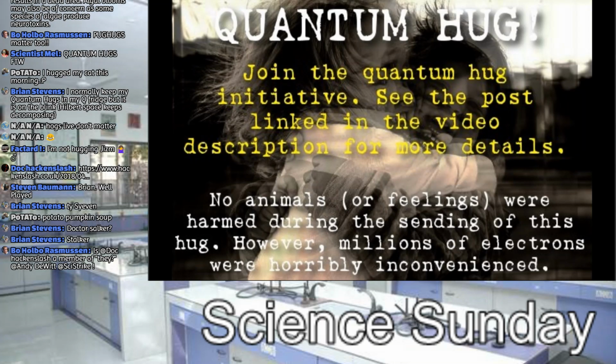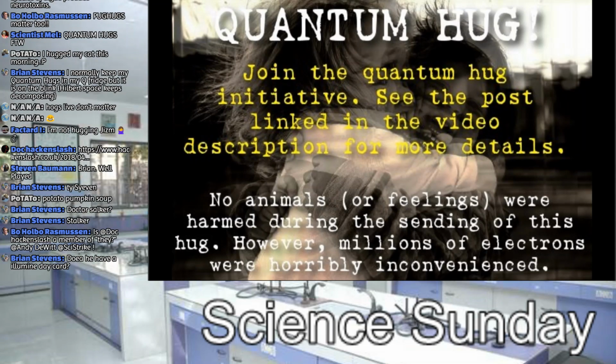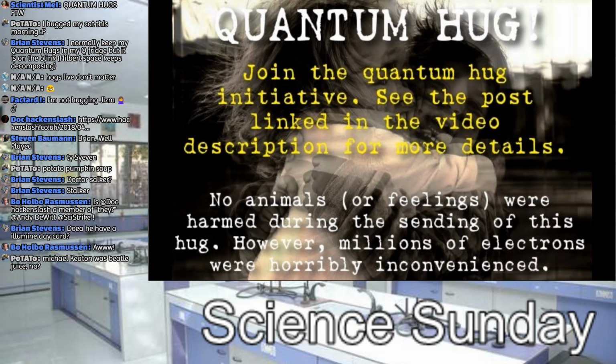Is there any zap? Not today. I told you I was operating while we only had the maximum 10-inch arcs last time was due to a mismatch in resonance of the two coils. As it turns out, the primary was resonant on a harmonic of the secondary, so it was still transferring power, just not as much as we'd like. So it does happen. I'm hoping to have my new MMC built shortly. We'll see how it goes.